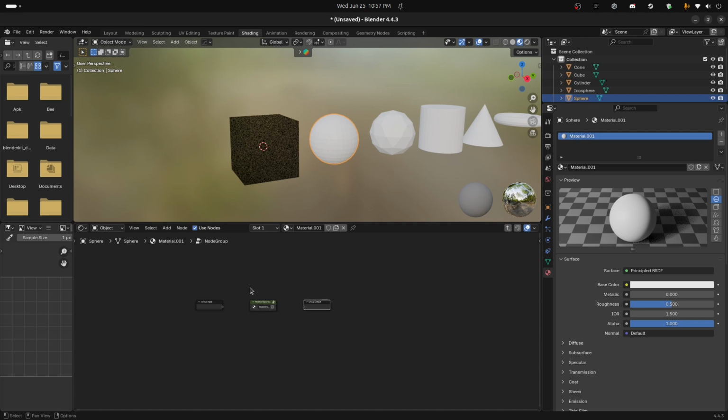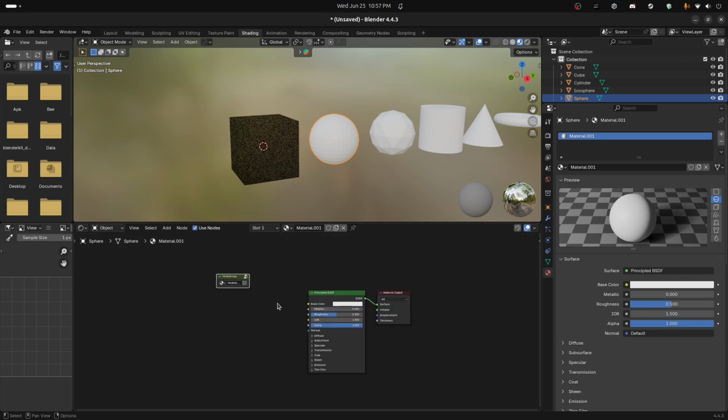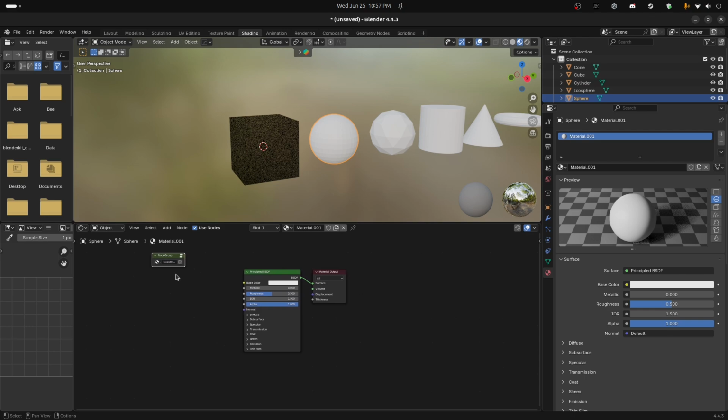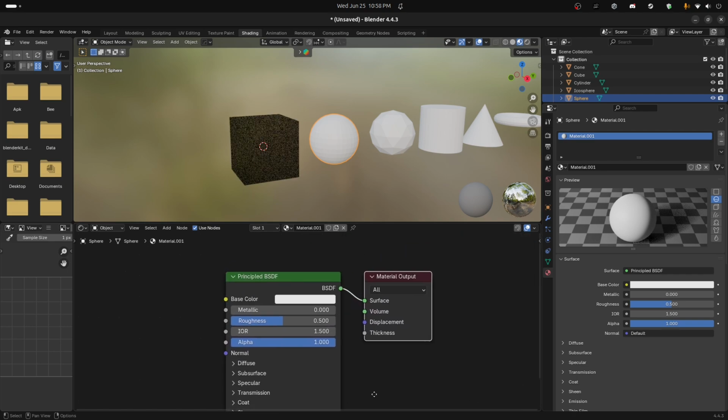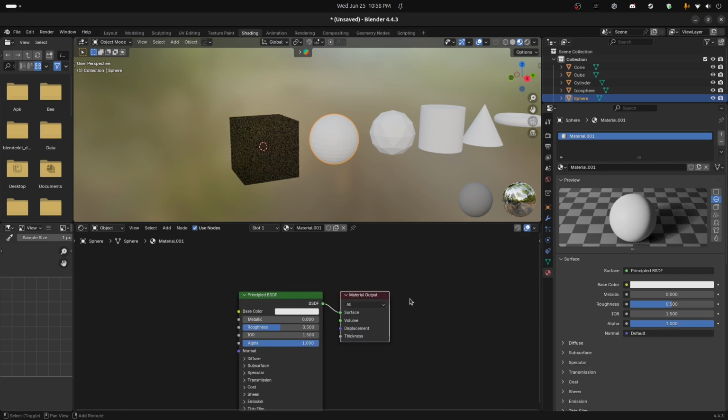There's a tab that goes in and out of this, but okay, I have to click on it. So you just have to click on one of the endpoints. Make a group. All complex, uber complex shader graphs and networks of shaders combined into this material output. So everything has to funnel through this material output.